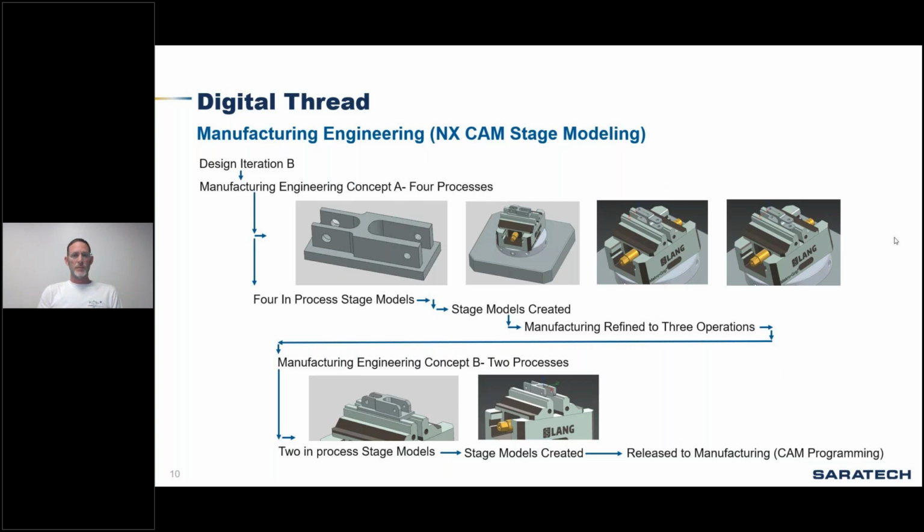NX is built right out of the box in such a fashion that you really should be letting the software just do everything for you. You should be letting adaptive roughing run for you, cavity milling, rest milling. You should be running feature-based manufacturing, and then you should be selecting those surfaces, right-clicking, and making a suggestion, tuning the suggestion up to where everybody has the same rules, everybody's creating the same holes, the same tooling, the same operations, same roughing strategies.